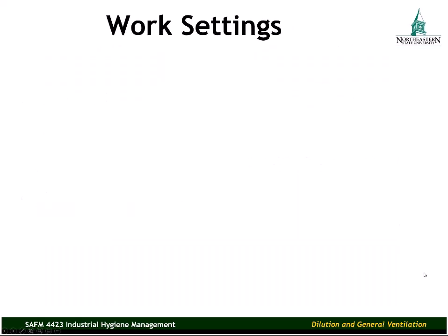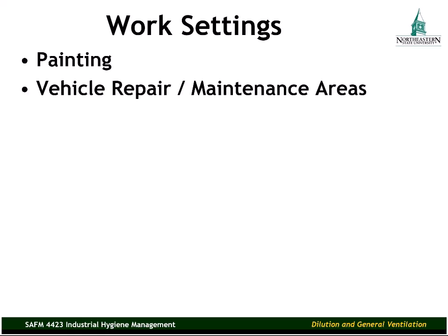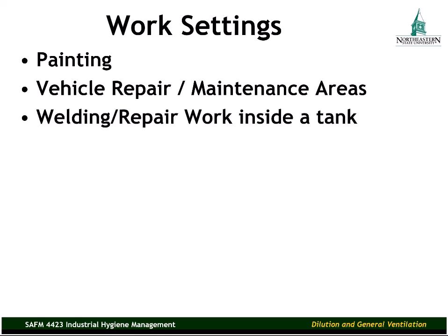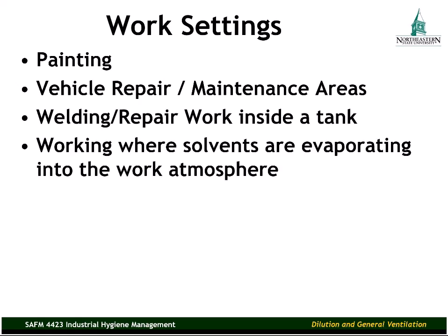Speaking of work settings, here are some example operations where dilution ventilation could be used. Painting, vehicle repair or maintenance areas, of course welding, repair work inside of a tank, or any kind of operation where you have solvents evaporating into the work atmosphere, whether it's methyl ethyl ketone or acetone or some other cleaning solvent.